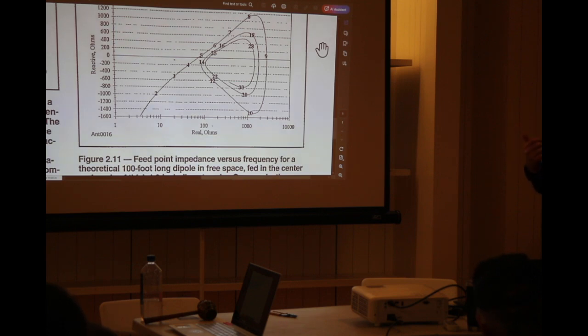The way we do that is we take our VNA and look for a quarter wavelength. We take a transmission line and adjust the frequency till it's a quarter wavelength long, in other words, it takes one lap, okay? So we have half a lap around the VNA. We know our transmission line is a quarter wavelength long at that frequency.